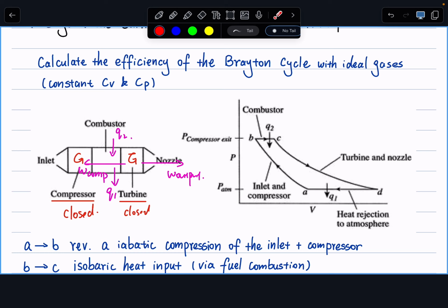All right, so in this original first law of thermodynamics, both my Q and W refer to heat into the system and work done on the system. But in this setup, we know the work is output by the system, so that work output equals negative W. So when we plug it back into this equation, we have Q1, Q2 minus the work output equals 0.